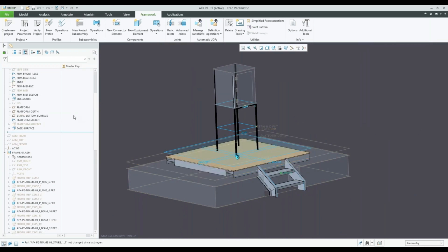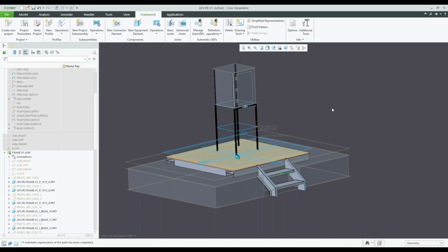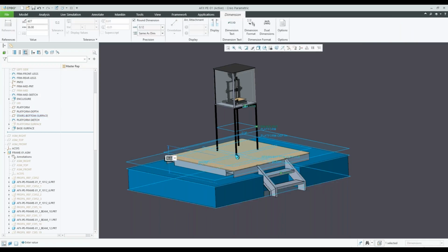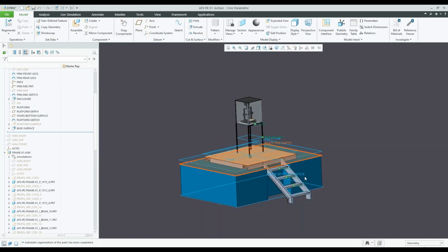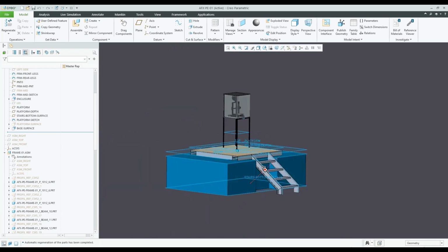And again, if I adjust that plane in the skeleton model, stairs bottom surface, and I modify that from 2 feet to 3, for example, you do that again. Make sure I get out of this and go back to top level assembly, make sure it's activated, and I'm going to find that plane. Let's do 48. And there it is. So now it's 4 feet, and now we have these 4 steps. It's pretty neat.